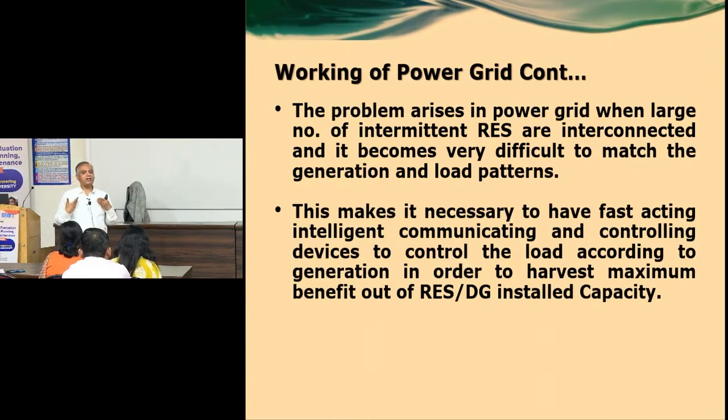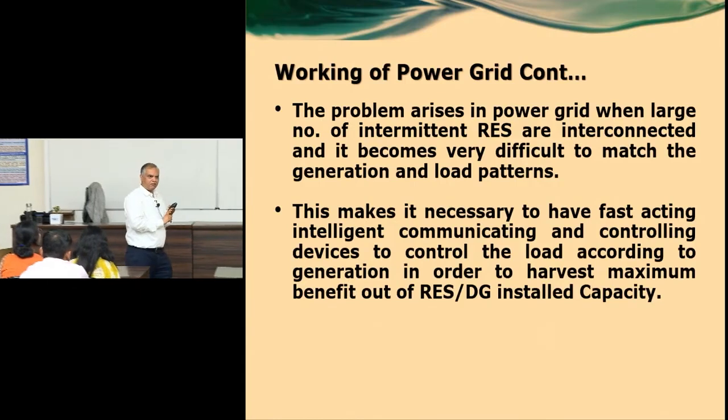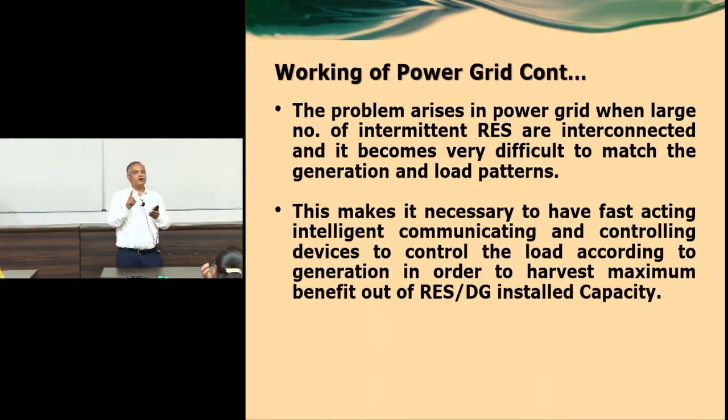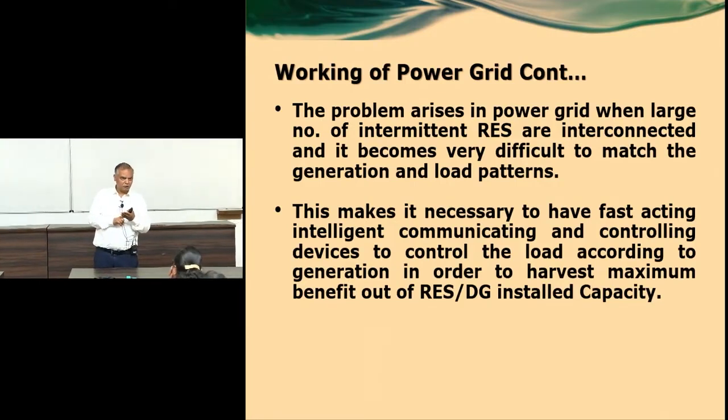ID and IQ is always in your hand. You know the kVA rating or MVA rating of the inverter. You know the voltage level of the inverter through the point of common coupling. So as an engineer, you can do a very small calculation. You have to calculate the real amount of current only, and you can divide the current further into its active and reactive component.